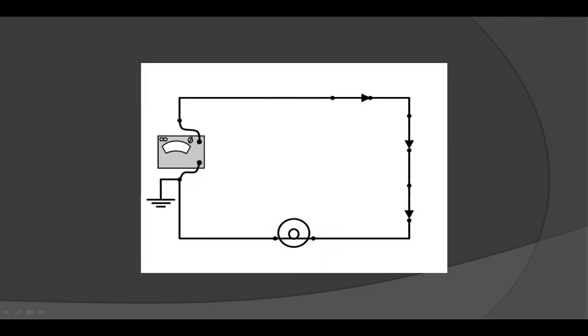But first, let's take a look at this circuit, which contains 3 switches and a lamp for a load. The device on the left is an ohm meter measuring resistance to ground. Let's put a short between the first and second switch. When we measure resistance with an ohm meter, we get a path of low resistance through the short. If we open the first switch, our path through the short is broken. When we reclose the first switch, our path for current returns.